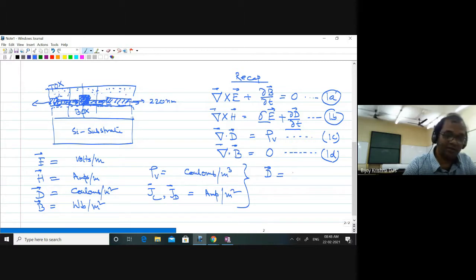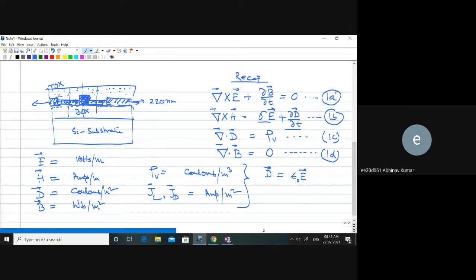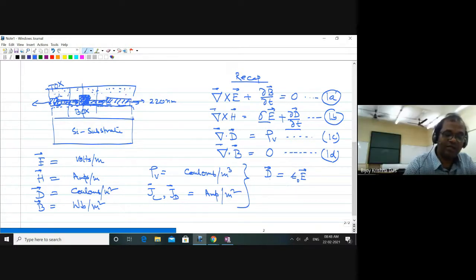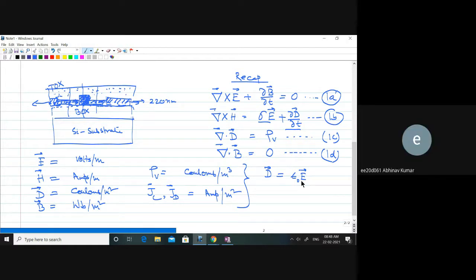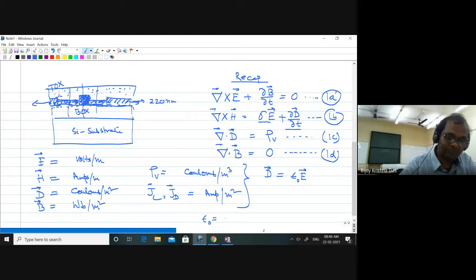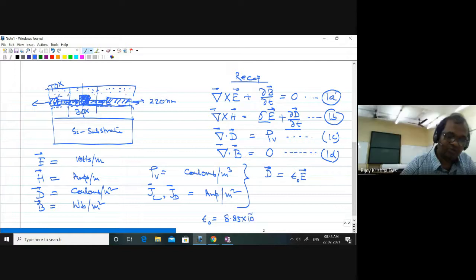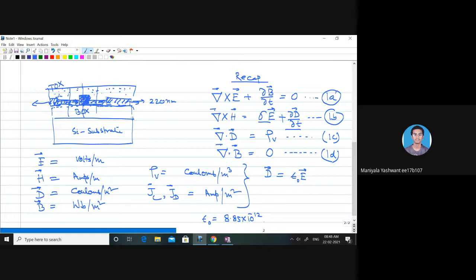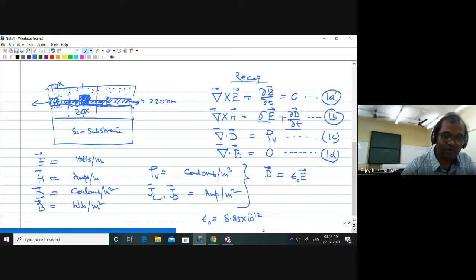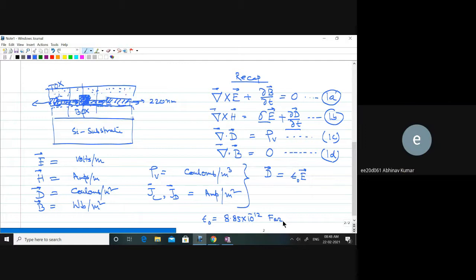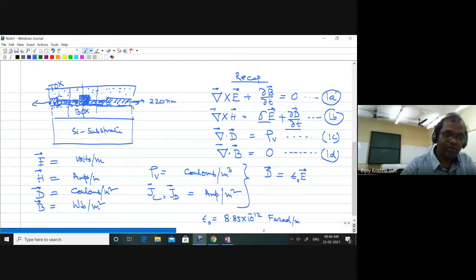Normally it is dependent on the electric field. If it is free space, we define D like that. Epsilon 0 is what? Permittivity, sir. Permittivity. What is the value you know in free space? 8.854 times 10 to the power minus 12. Farad per centimeter? Really? Farad per meter. If it is minus 12, it is farad per meter. Okay, this is free space.